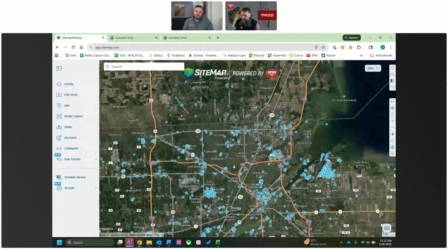Yeah, you could easily capture hundreds of acres a day with a drone. It's incredible how much space you can capture. A lot of times, we can just do a 50-acre site for a fairly small fee, and give you a lot of high-level navigational grade information, to put an aerial image in SiteMap and give you a rough idea of where the buildings are placed. But then we can use terrestrial scanning where drones fall short, or where we need additional detail and accuracy. That's where we can bring in laser scanning to supplement those large area drone captures.